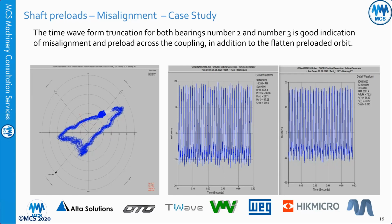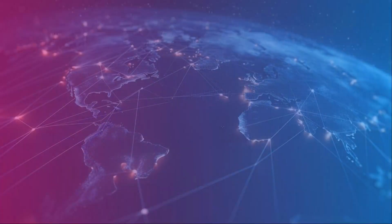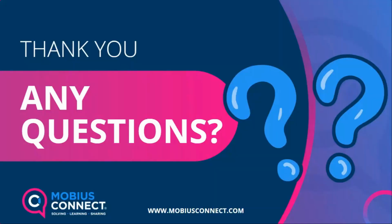Thank you. All right, this one might be a little number teaser for you. Do you know the ISO for the displacement readings? The ISO standard for the relative displacement is 7919, and you have 4 zones: A, B, C, and D. 0 to 90, 90 to 165, 165 to 245, and over 245. Okay, well, that was not a number problem at all for you. You had that memorized.